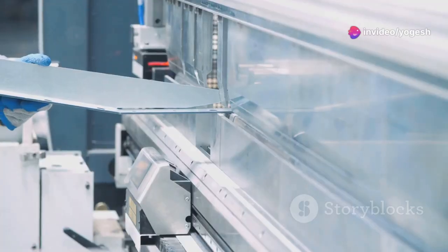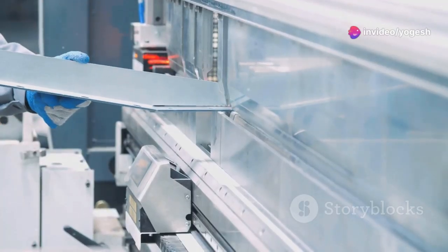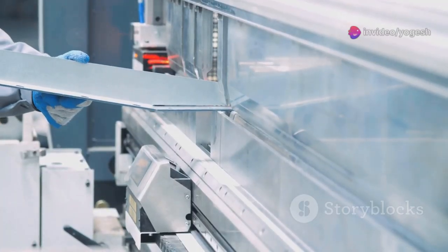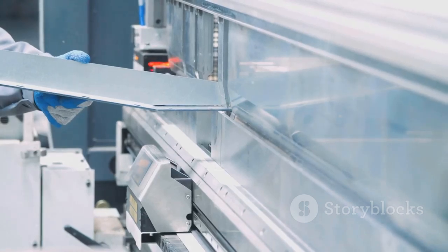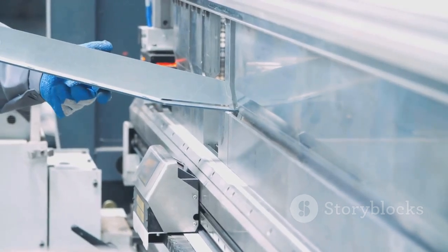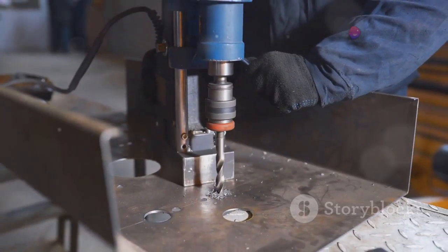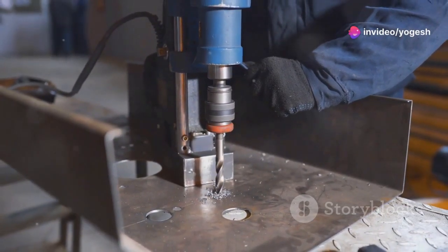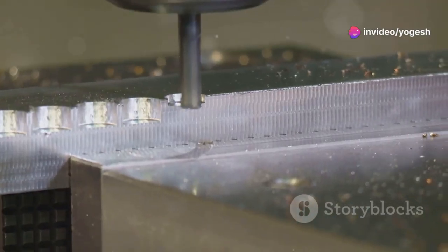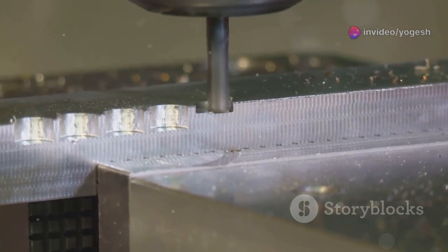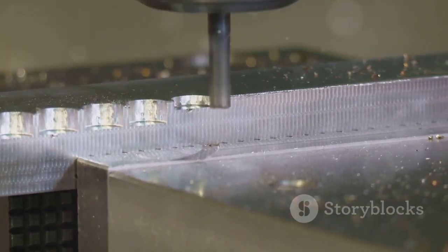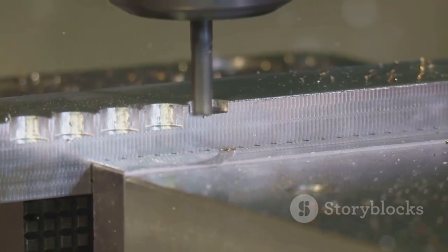The CAD software will automatically add bend reliefs and fillets at the corners, which are essential for smooth bends and to avoid tearing at sharp edges. Place all mounting holes at least 4.5 mm away from any bend line. This precaution helps prevent distortion or weakening of the material around the holes during the bending process.